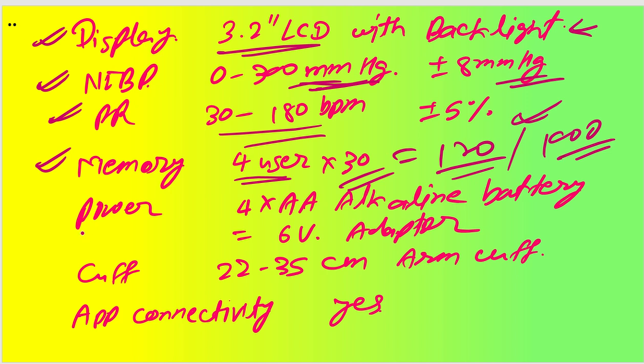Power, since it is a portable device, we'll try to power it through alkaline batteries. Okay, so 4 alkaline batteries we can put, so 4 into 1.5, that is 6 volt, will be there, or otherwise you can utilize a 6 volt adapter also, or we'll try to give a USB pin also. So through your laptop USB you will be able to do that, which will give you a 5 volt output. Okay,